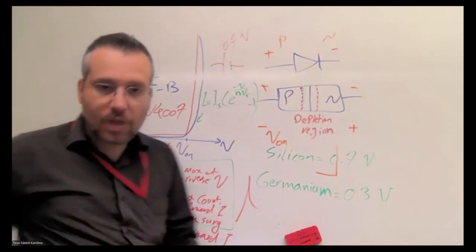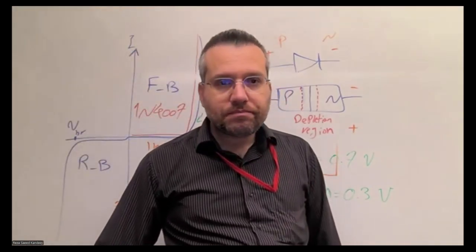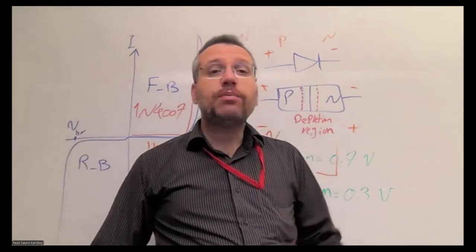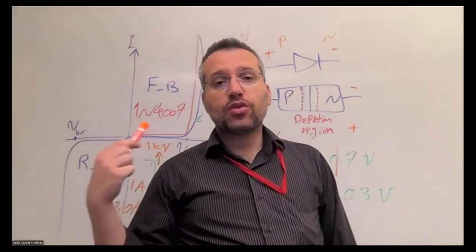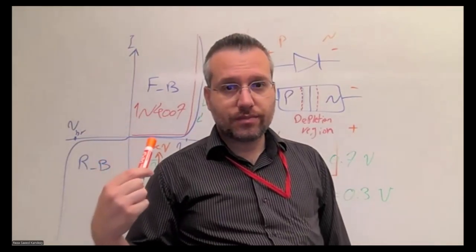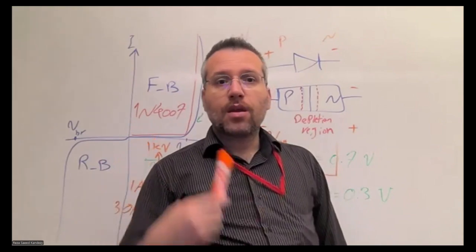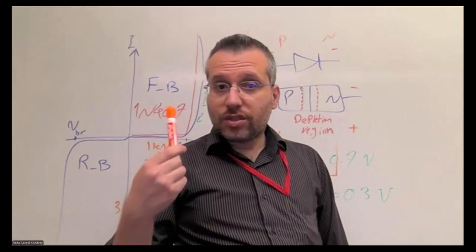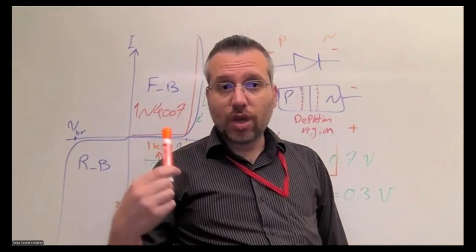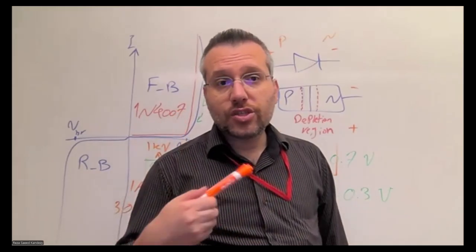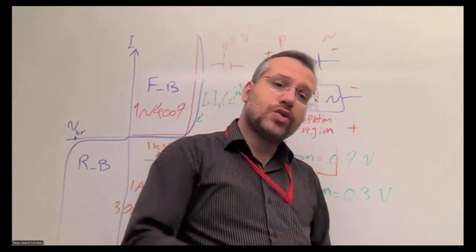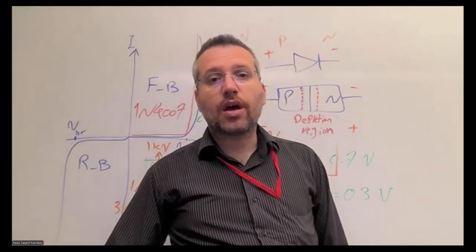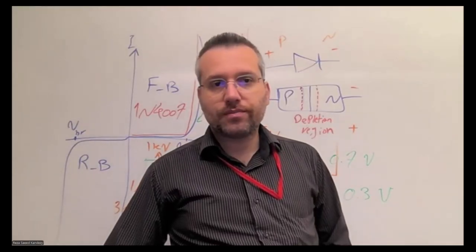Basically, before building any circuit, you must check the diode's characteristics. This is the tolerance of those diodes. We never design only for continuous operation. We have to consider transient events like surge.